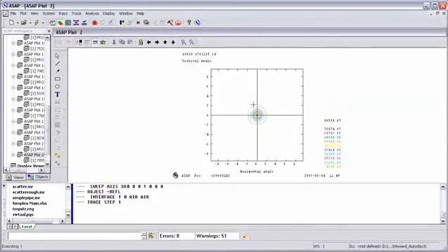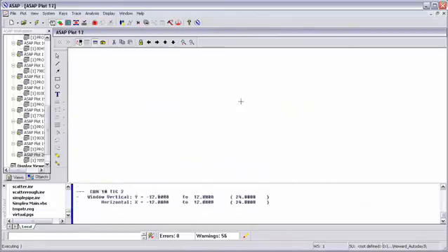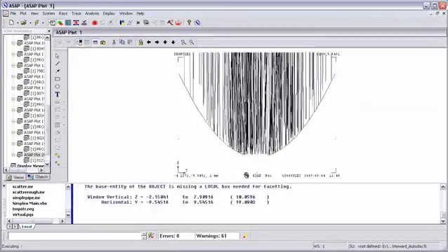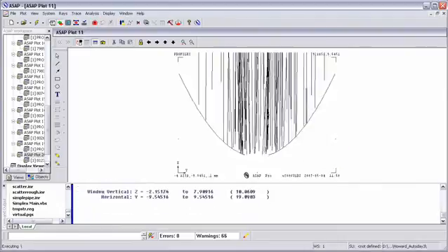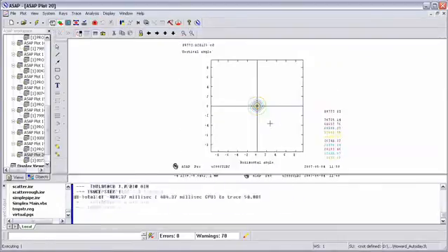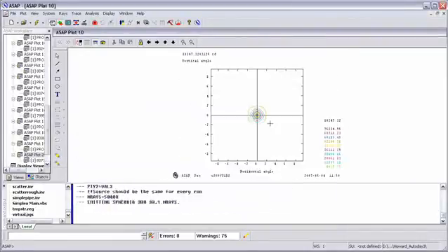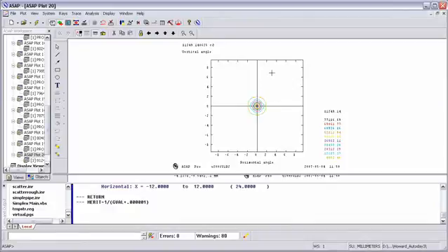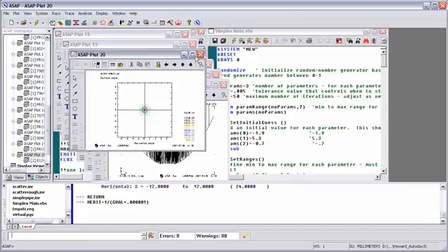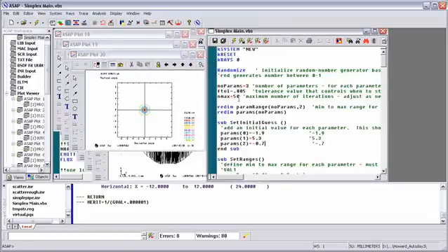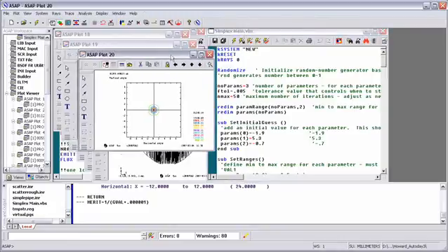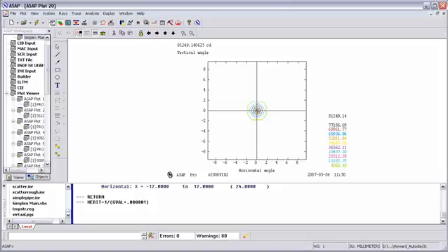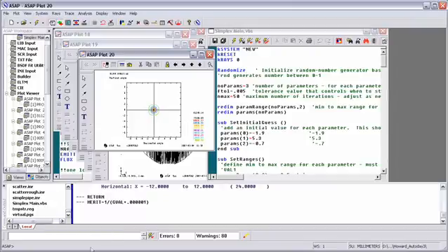If you recall the first simulation of the component, right now we're seeing center values of around 80,000 candela. The first simulation of our component had center values of around 29,000. So the system's increased fourfold in performance automatically through the optimizer. Okay, so the optimizer's completed running through its iterations. In this case, we asked it to only run a maximum number of 50 times. We could set that number higher if we wanted to be sure that we were finding the minimum. However, we've settled on a design that's given us 4 times the performance that we had originally.